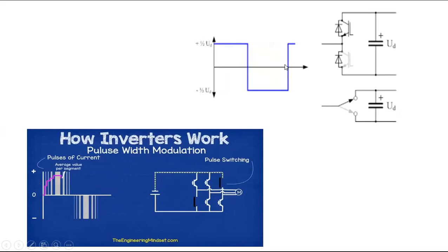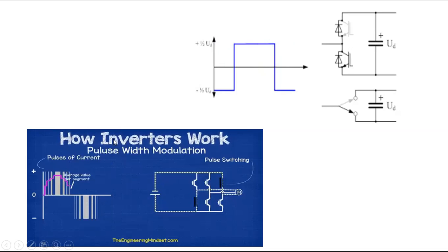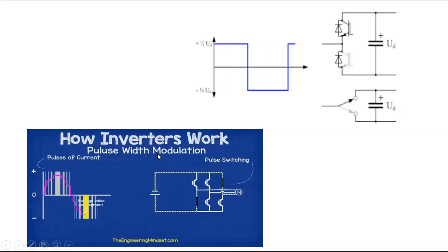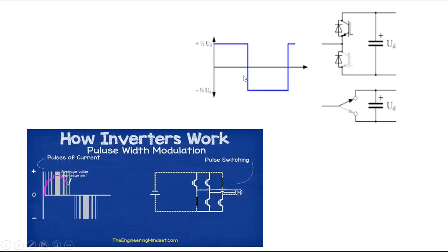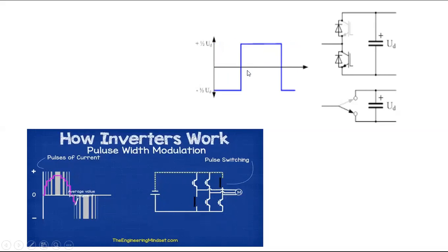Okay, now what we do, we use the concept. Now you can see the second animation. Pulse width modulation is the most important topic which we study in this unit. The inverter circuit contains a number of switches. This square waveform cannot be given to a bulb. If it is given to the bulb, the bulb will never glow. Any induction motor will never understand this square waveform AC signal. They understand a pure sine wave.